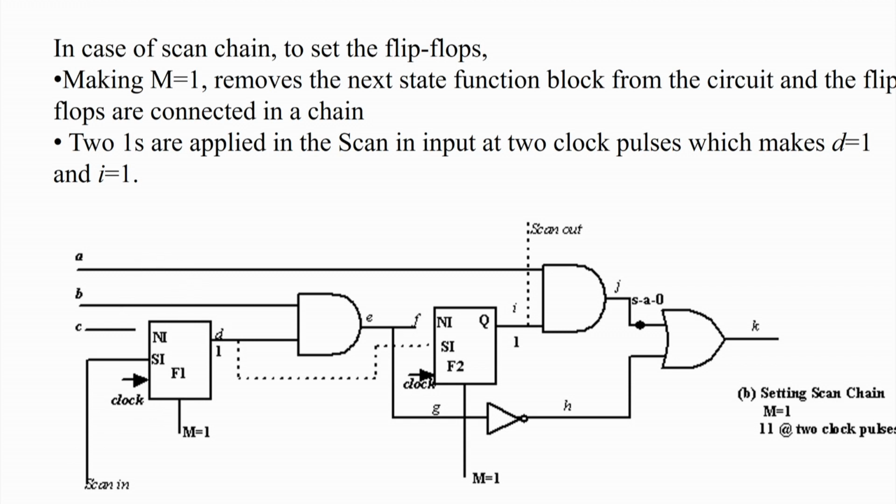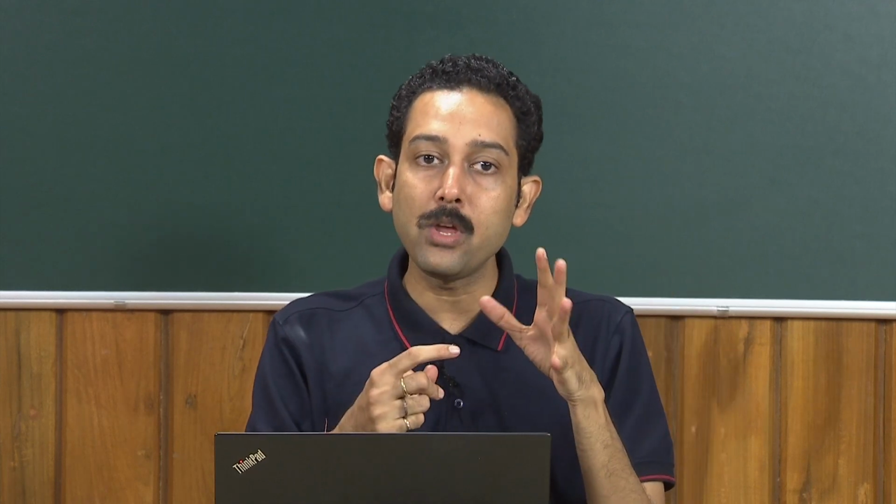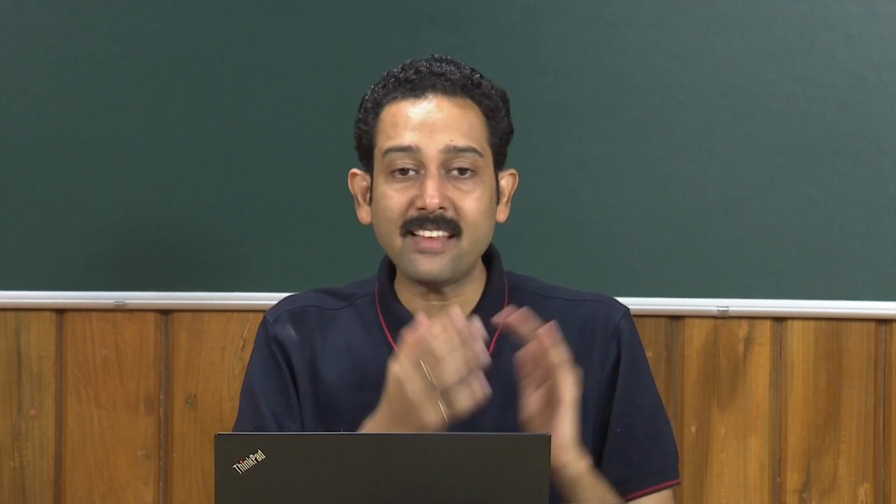Now both the flip flops are settled, but I have to apply 2 clock pulses. That is what the time is being taken. So I require 2 clock pulses to do this, but the mathematical computation is very simple in this case. When you see, for testing, optimizations are at many phases. One is the test generation time optimization, that is ATPG algorithm optimization. And the other is how much time you require to execute the test plan. In scan chain it is very simple.